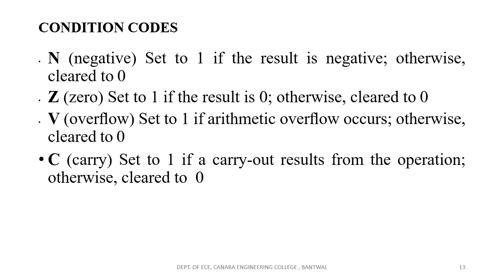If the negative flag in the status register is set to 1, then the result of the operation is negative. Whereas if the result is 0, then the zero bit in the status flag is set to 1, which indicates the result is 0.